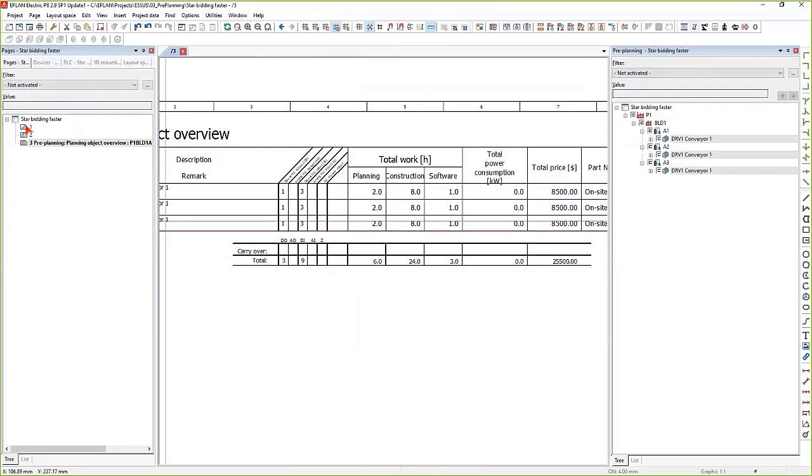I just have an understanding of the control systems that I'll need. I also have a number of IOs or signals needed for that particular system. So there I can already start sizing my PLC system and maybe go to the various different PLC vendors and ask them what type of PLC could support that type of system.